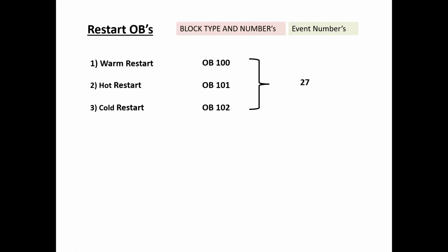Warm restart means it refreshes your memory. It does not reset retentive memory, which retains the previous value. But it resets RAM memory, which is non-retentive, resetting it to zero. Those RAM memories reset to zero, whereas ROM memory is not reset to zero, it is just refreshed.